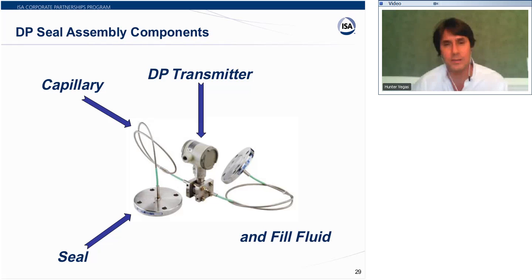What's important here to know is that once it's put together, it's put together. And so if you get the wrong fill fluid, or you pick the wrong capillary, or the seal doesn't fit, then you're toast, and you have to send the whole thing back to get it fixed. These are generally not repairable just because it's so difficult to do. And so getting it right the first time is really your only option here.